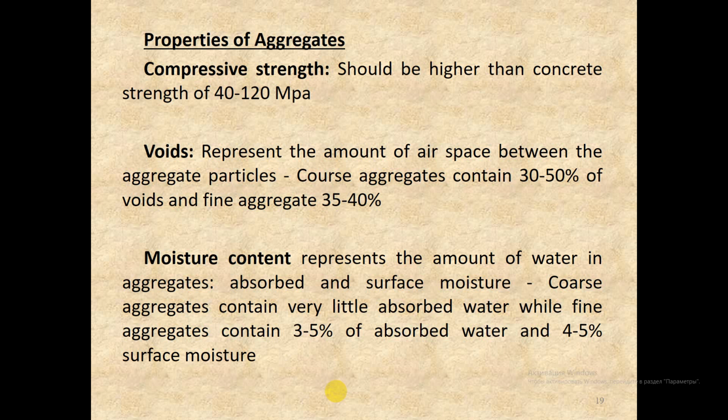If it's impossible to provide a concrete surface below the aggregate, the bottom 300 mm of aggregate should be discarded, as contaminants from the ground can affect this zone.